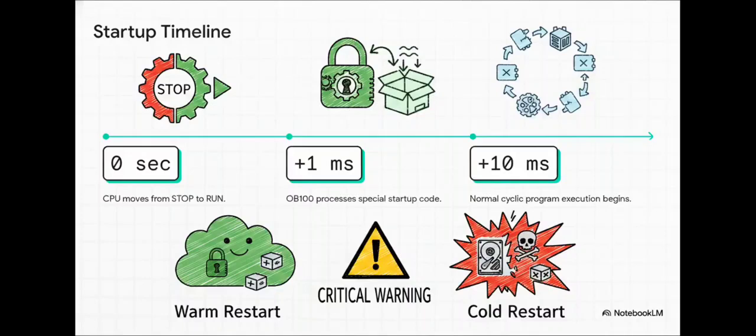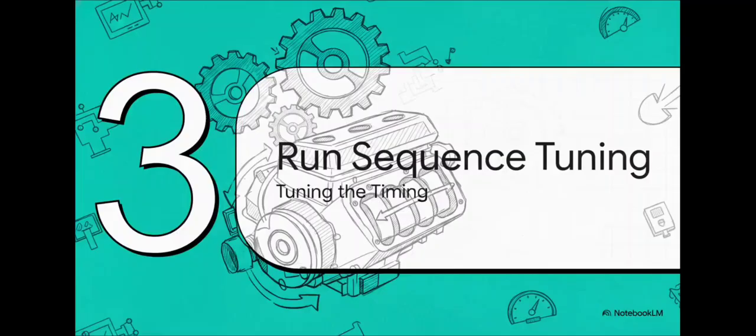A cold restart is incredibly dangerous. If you execute a cold restart, all your vital process data is permanently destroyed and reinitialized, so always know exactly which startup you are initiating. Moving on to Section 3, Optimizing Run Sequences, Tuning the Timing.